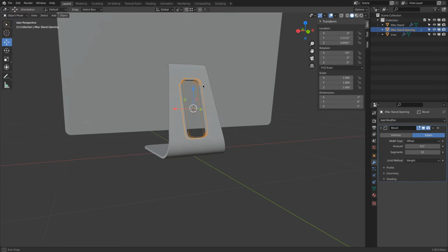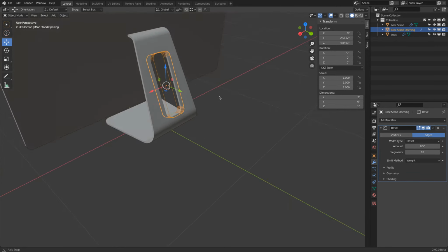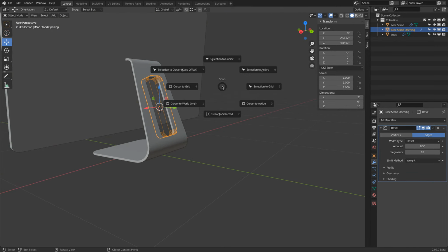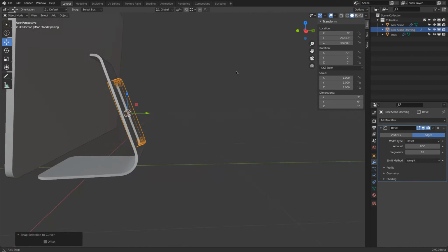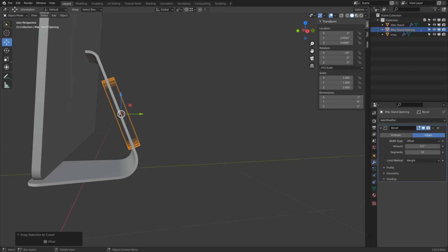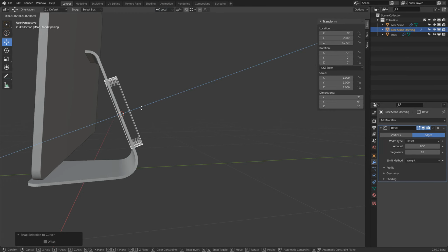And this one here, I now select in object mode, Shift S, and say selection to the cursor. So now, because of this being very thick, so 1 inch, it perfectly intersects my part, so it does not matter that this is a little bit left or a little bit right.